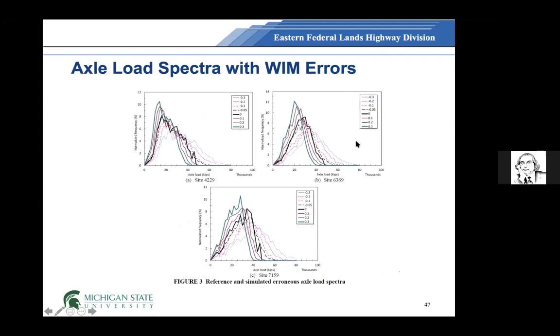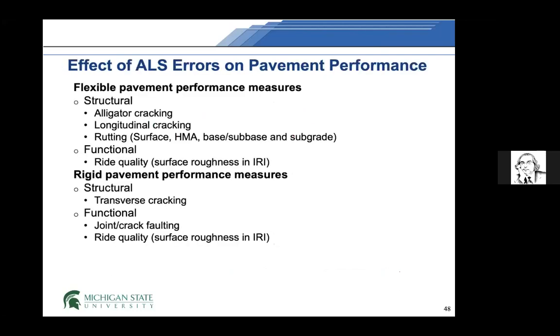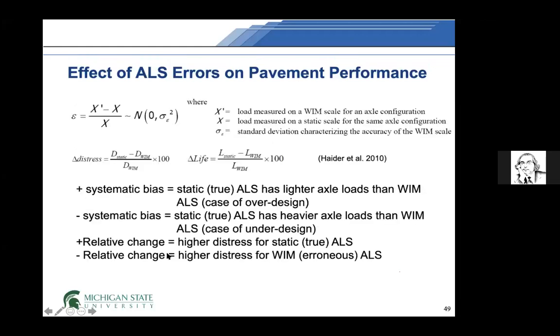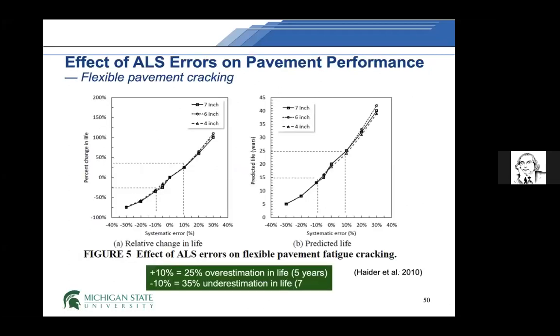I can use these load spectra in the Pavement ME to predict alligator cracking, longitudinal cracking, rutting, and ride quality, and transverse cracking for rigid pavement, faulting, and IRI for rigid pavement. Now, I'm going to explain that here.